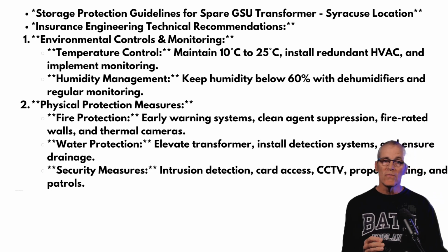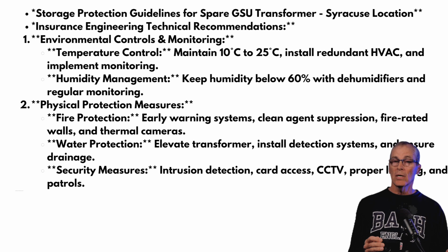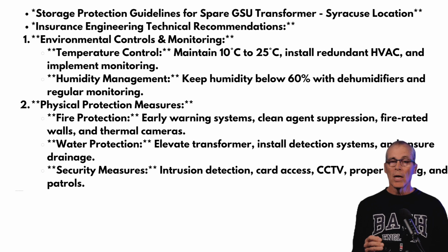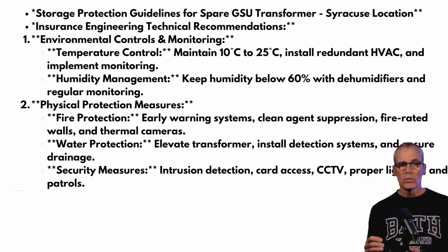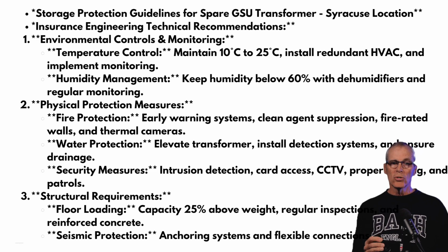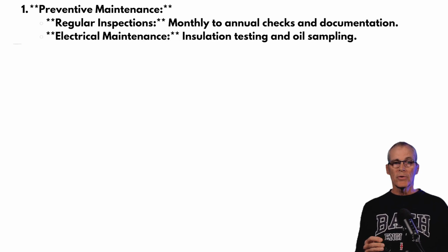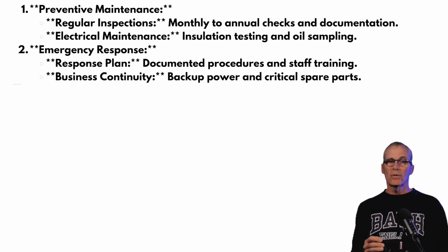Humidity management, physical protection, fire protection. That was interesting, that it just off the bat recommended fire protection without really even talking about ignition sources or fuel loads. But having a GSU in there, it's probably going to be loaded with oil, so it's a good suggestion. Security measures, the loading, seismic protection, maintenance, emergency response.